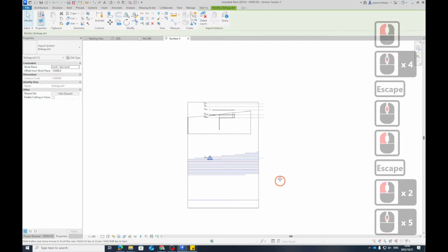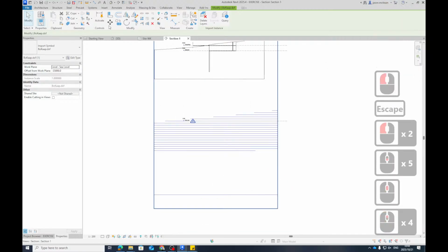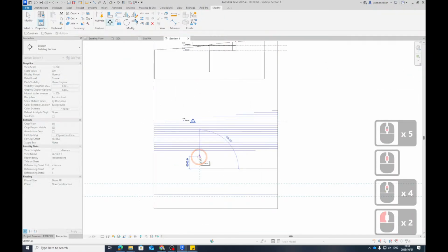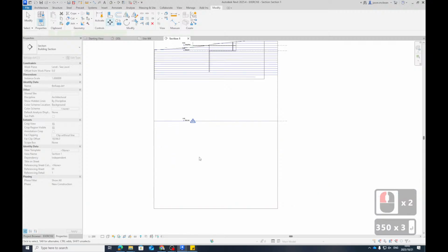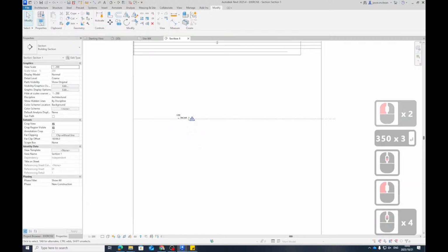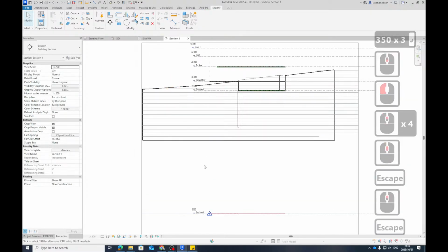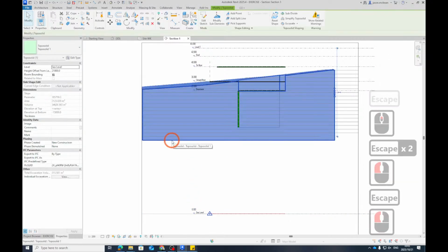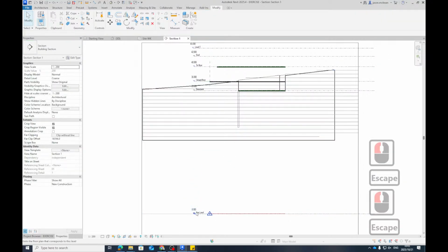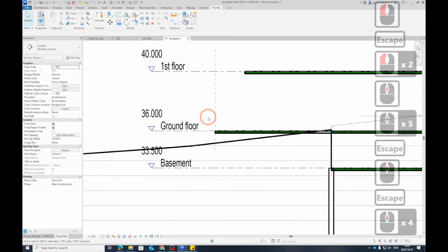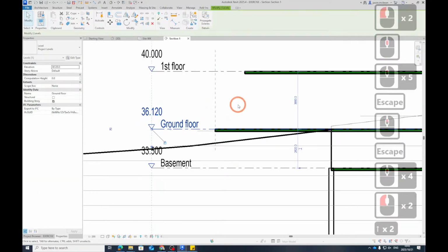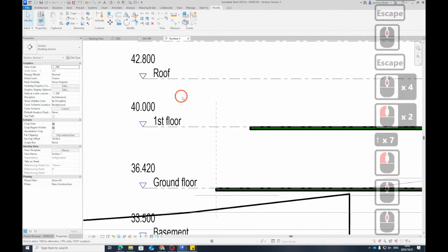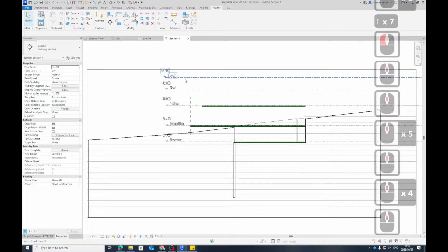This is that CAD file that I gave you. That also moved down, so that has to move up by 35,000 as well. Okay, now we're back, and you see it's telling me everything's back. So now this and this are back where they should be. But this is your sea level, so we fixed that issue with the ground. So the rest of these levels now, you can now move independently of that other one that might interrupt you.